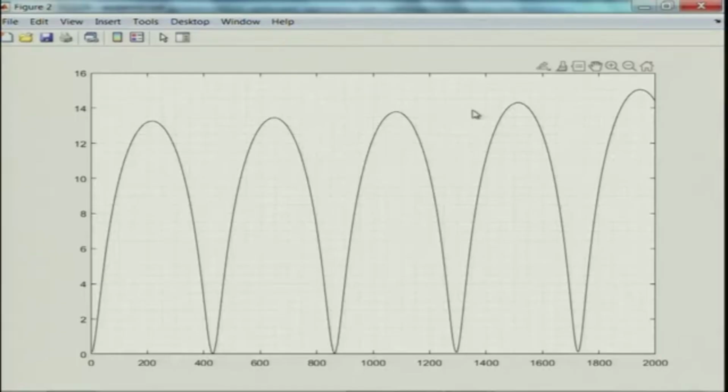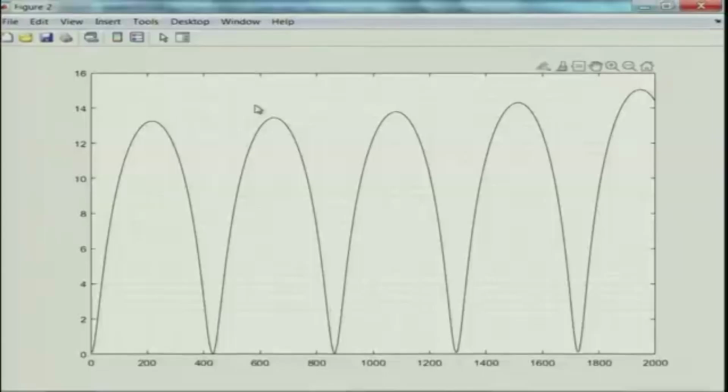However, I must point out that the transmission loss performance of an ECTR, that is an extended concentric tube resonator, will be quite different in terms of tuning of the length compared to a simple expansion chamber with neck extensions, for the simple reason that perforate impedance has a major role to play. You notice in the slide, the transmission loss is not identically 0, although it tends to that; practically it is 0, but there are troughs that are lifted.